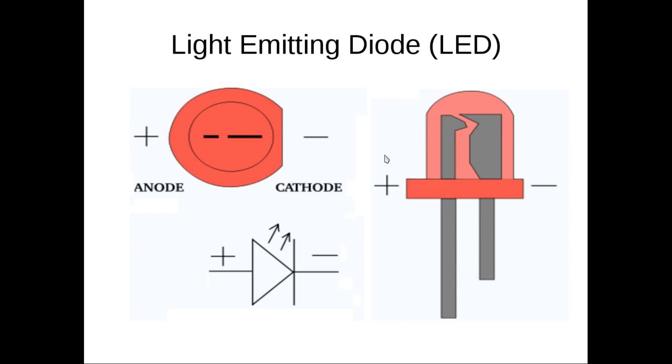And if you look inside your LED, you'll notice that it has some parts inside of it. There's a larger piece of metal inside the plastic case, and that is called the cathode. And usually, if the leads have not been trimmed on it, the shorter lead is connected to the cathode. And then the other piece, which is a smaller piece of metal inside the plastic case, is called the anode. Normally the anode is connected to positive and the cathode is connected to negative.